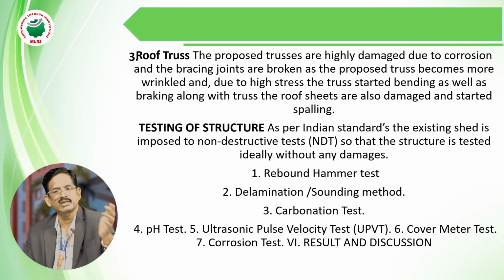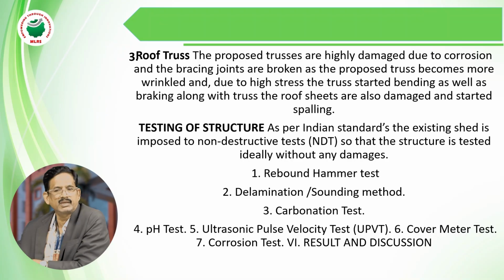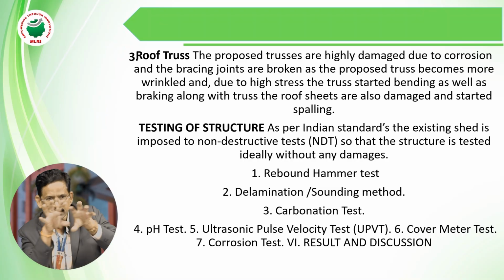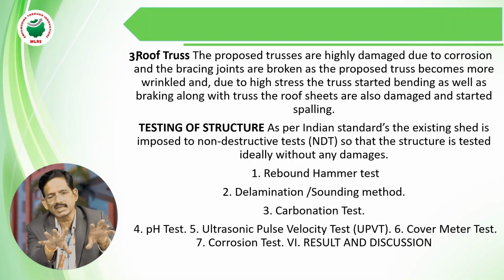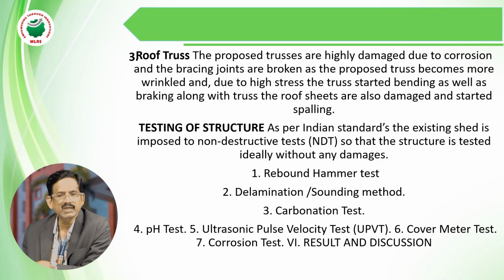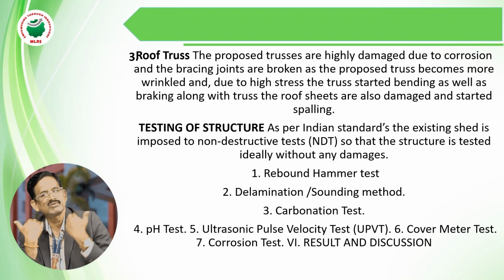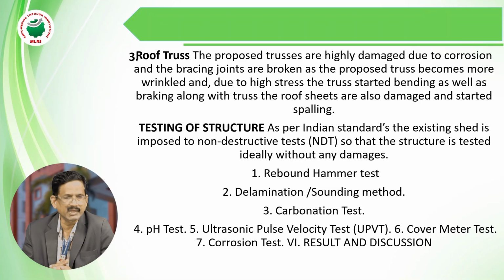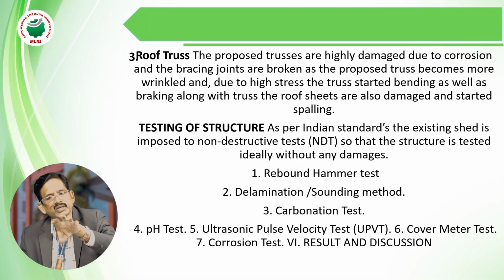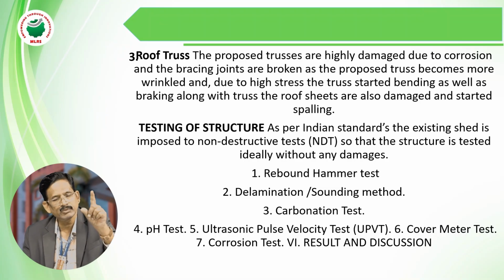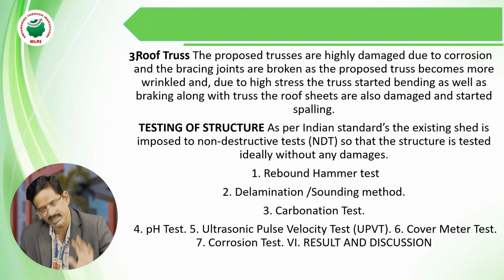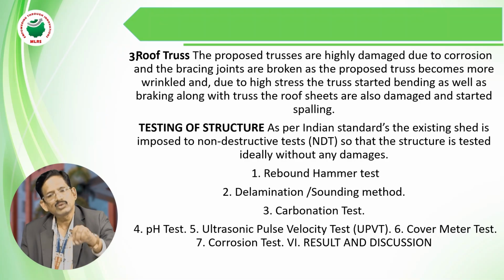Design of the column is different, execution of the column is different, maintenance of the column is different. These three are very, very important. We have to execute as per the design only, don't deviate. If any maintenance is needed, you have to do the maintenance properly and immediately, otherwise deterioration will start. Is it clear or not, my dear students? So that's why you don't want to deviate from the design strengths or design values. Suppose 20 mm is designed, you should use 20 mm. If 16 mm is designed, you have to use 16 mm. If you are going to use 8 mm rings, you have to provide only 8 mm. Don't go for 6 mm, don't go for 10 mm either.